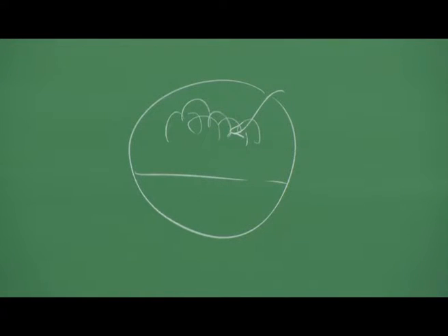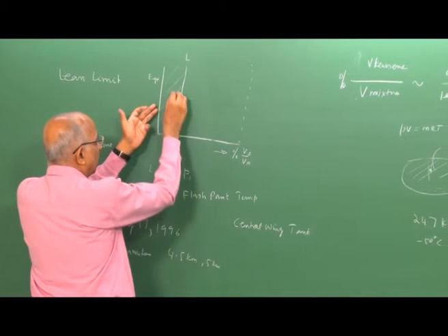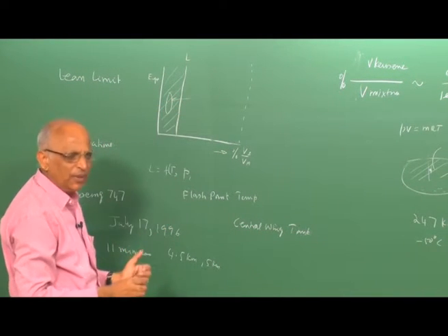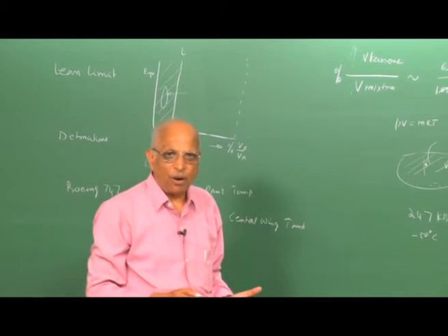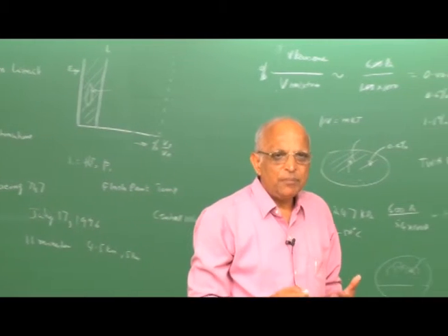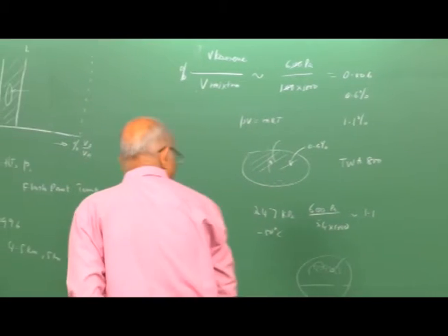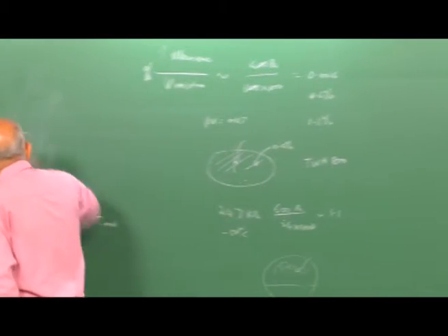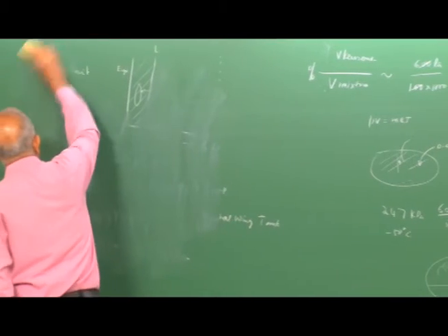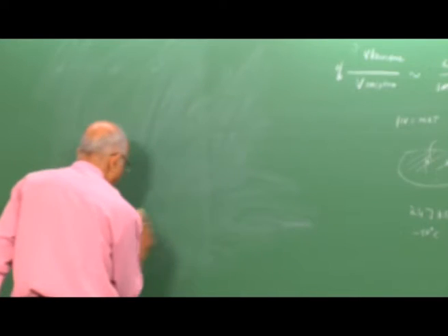Sort of, I introduce some inert gases such that I shift the concentration of volume of fuel divided by volume of mixture to this zone, which is non-flammable. Therefore, maybe we should take a look at this, and let us work out one or two small problems on how we make a mixture inert and go ahead with this. Therefore, in the problem what I do now is a small problem relating to how much quantity of inert gases we should add in order to make a mixture not flammable.